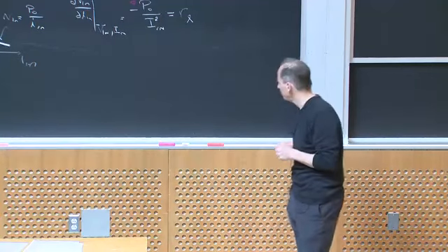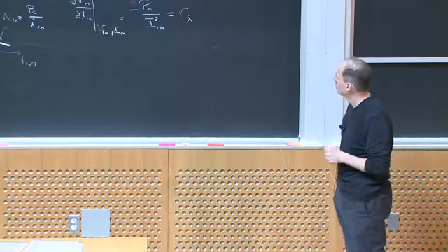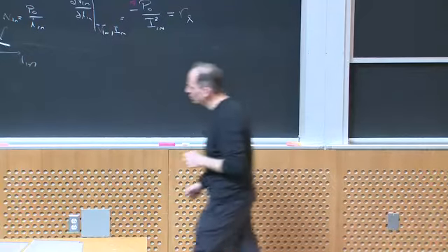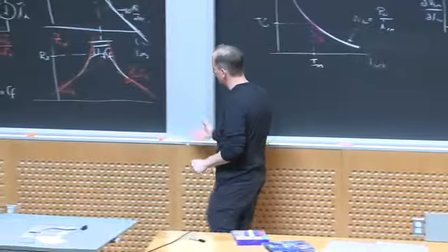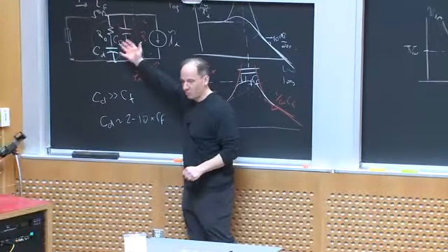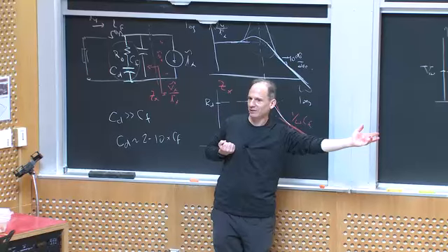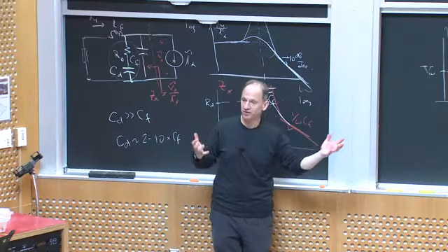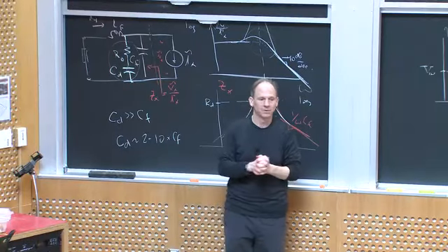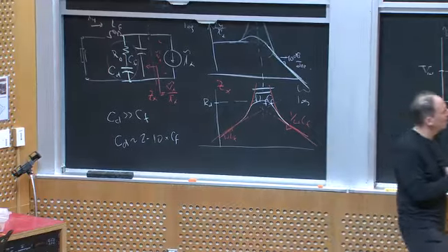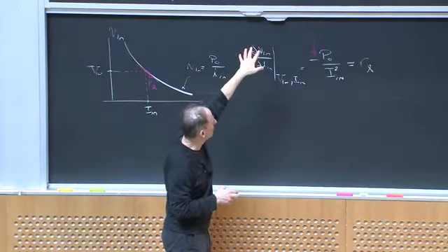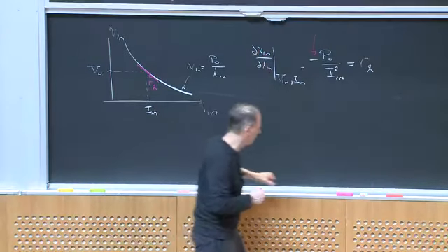Generally, the reason we obsess over our filter's output impedance is because I need to keep it small enough that when it looks into a negative input impedance, effectively a power converter, the whole system is going to be stable.